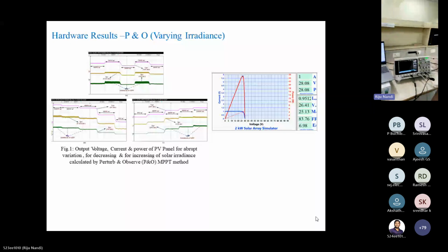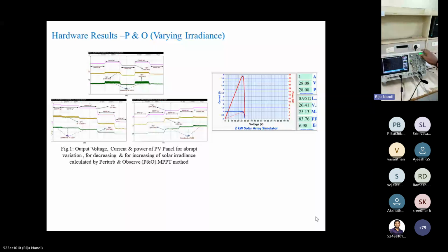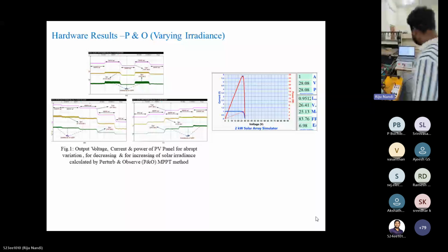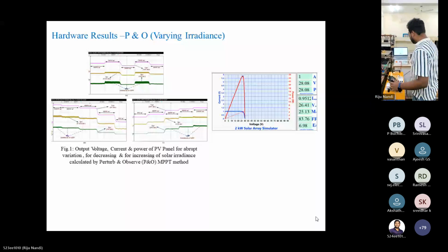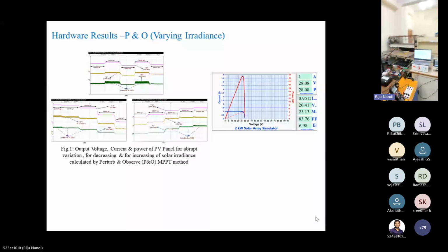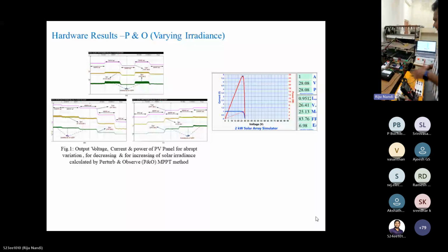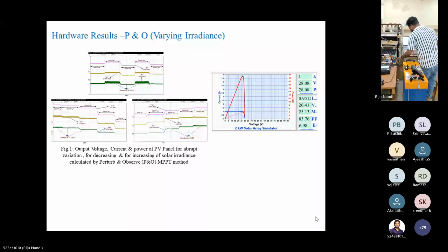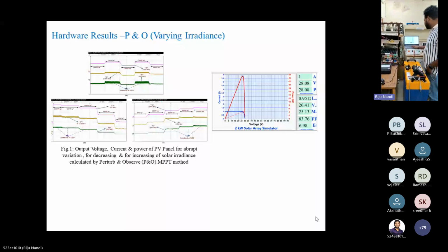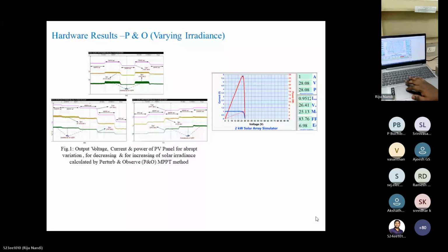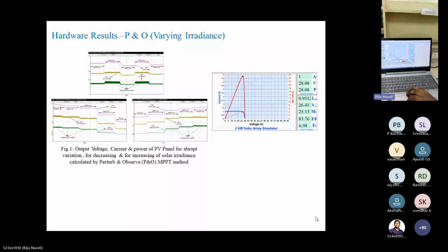This is the DSO, to supply the Arduino Mega, and for the duty pulse and current and voltage. This is the driver circuit and supply circuit. I will give 30 volts, and the current rating is 1 ampere. ISC is 1, VOC is 30.